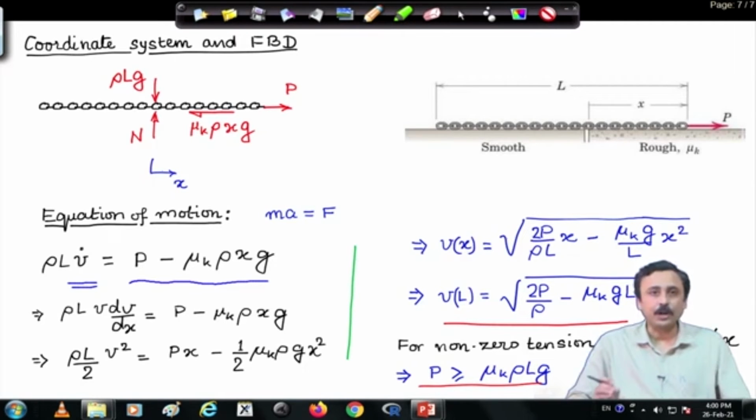So, if you do not brake on all the wheels, then there will be a collapse of the train. There will be tremendous compressive stresses developed between the coaches at the links, and that may lead to accidents. So, in any long train, you have to have braking on all the wheels.